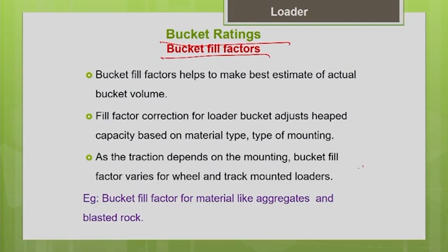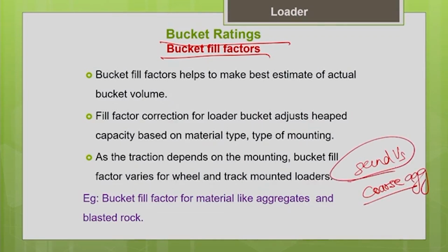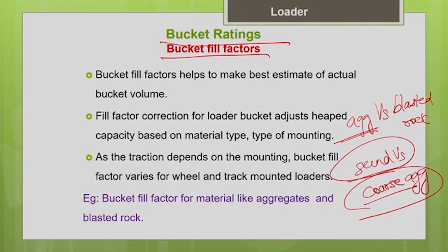If you compare sand with bigger size coarse aggregate, sand has better filling ability. Similarly, when I compare aggregate versus blasted rock or shot rock, obviously aggregate will have better filling ability. So, the filling ability of the material into the bucket will vary from material to material.